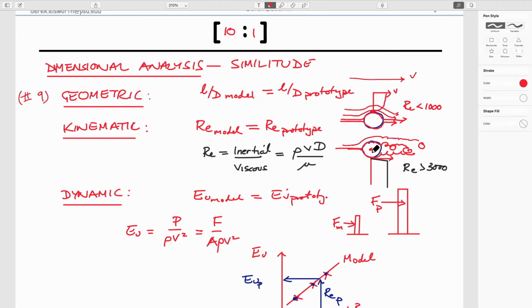So this is the classic idea, I don't know if people are doing it in this class for their project, of why a golf ball is dimpled. A dimpled golf ball makes the surface rough. You'd think it'd be slower going through the air and it would take more force to push it through the air. But what the dimples on a golf ball do is make it turbulent much earlier, at much lower velocities, and at those velocities this is much more efficient in pushing it through the air because you have this slip region which is really quite thin, and so you're not dragging against the viscosity.